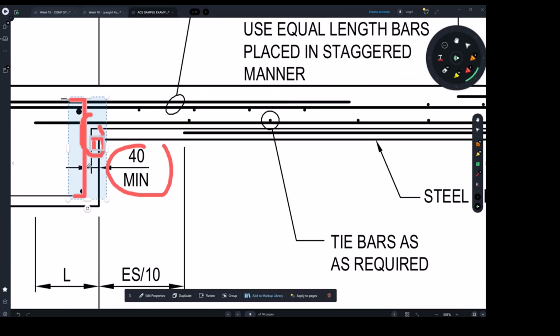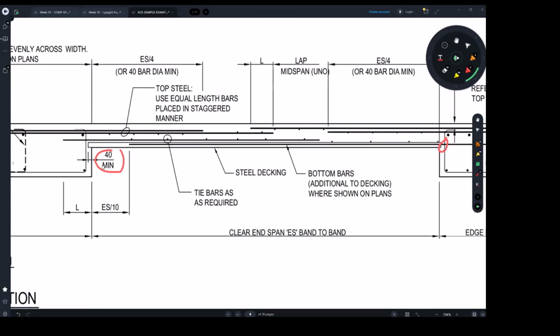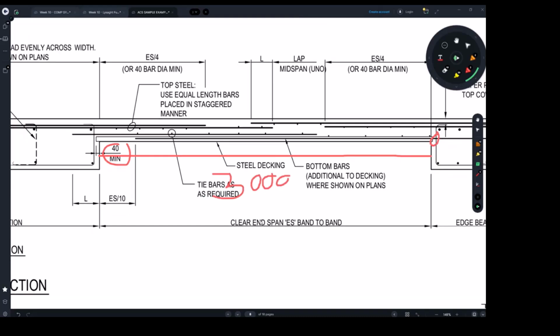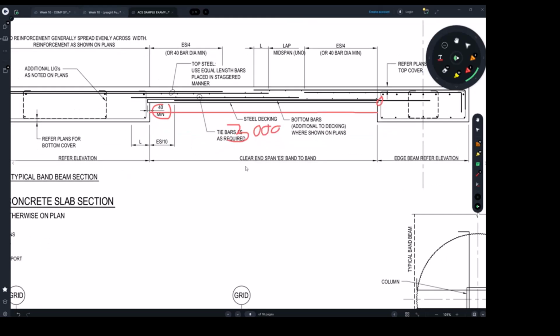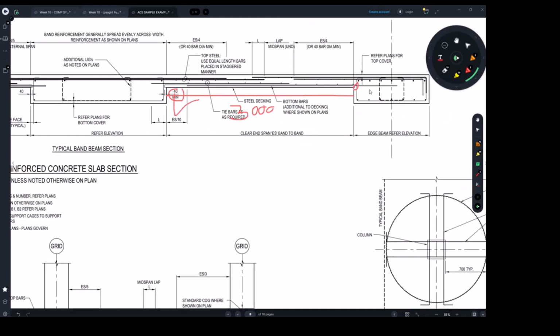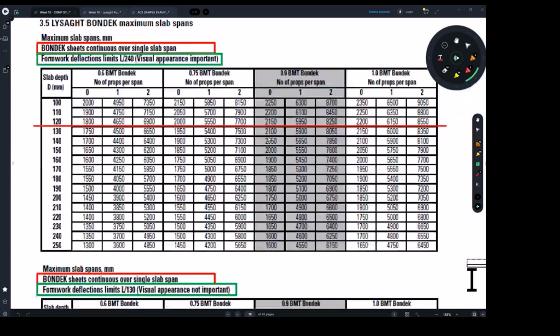Right? So going back to what I was talking about, I said to you, assume the span here is 3,000 or 3 meters, right? And I just said 3,100, allowing for those ends, which is 3,080 mil, but let's make it 3,100. So if we have 3,100, can you tell me what option I can use here if my slab thickness was 200 millimeter?